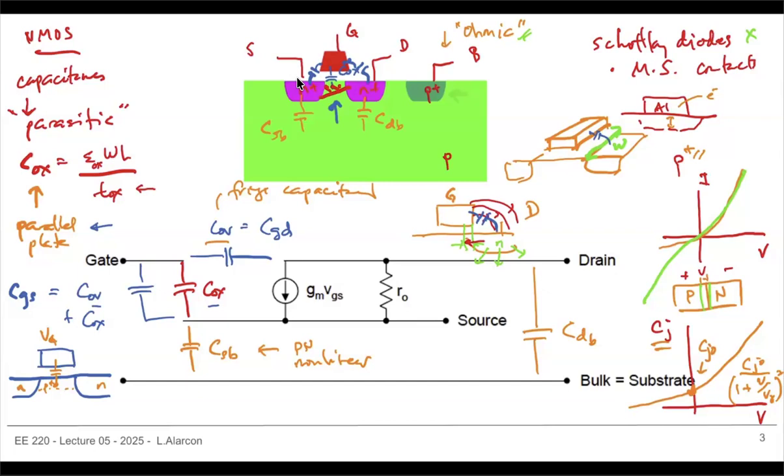But as soon as you deplete that, you have very little charge. And what happens is you actually get this capacitance and the capacitance of the P-type region. So you do get a certain amount of bulk capacitance over there. Then that reduces the capacitance because now you have a capacitance in series.